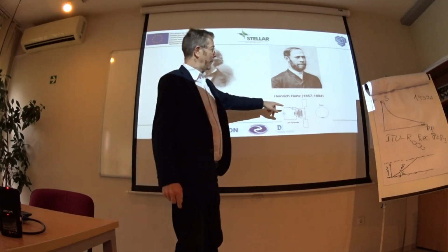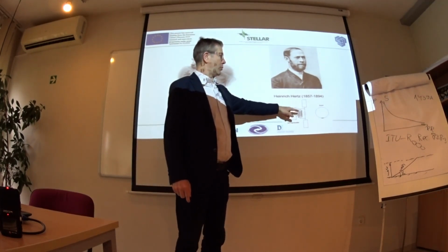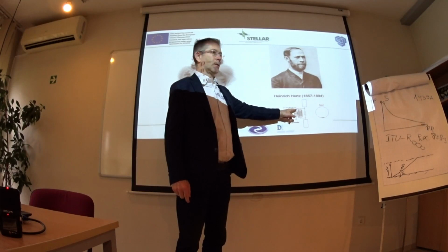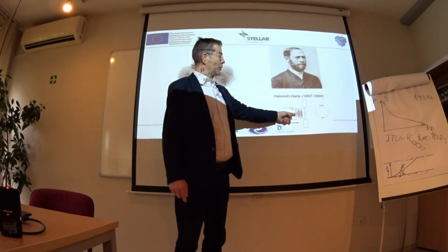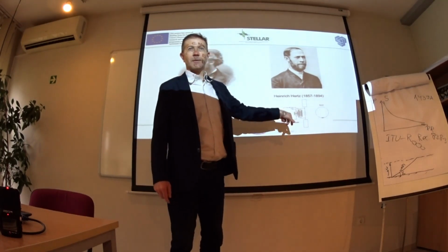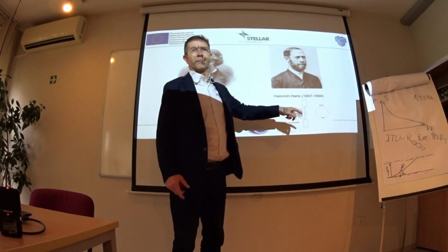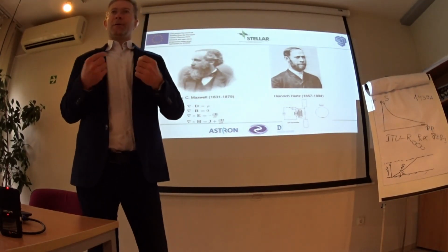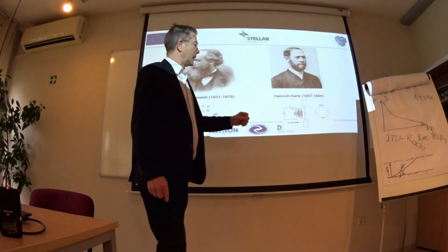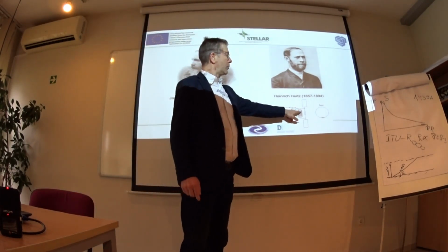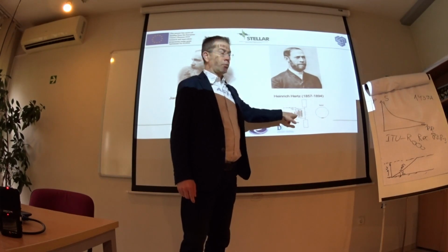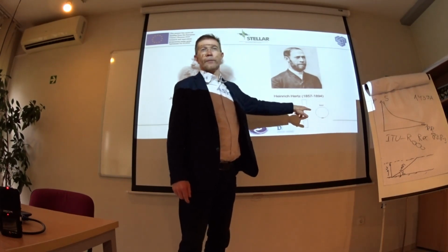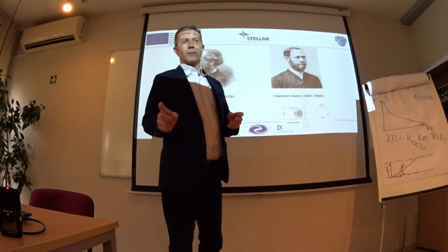When we close the switch, or open the switch after the coil is charged, oscillations start in this circuit because it's a resonant circuit. And once the oscillations start, the magnitude of the voltage is amplified through the transformer coupling.